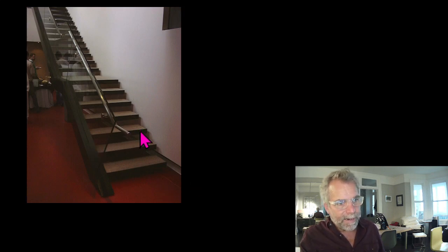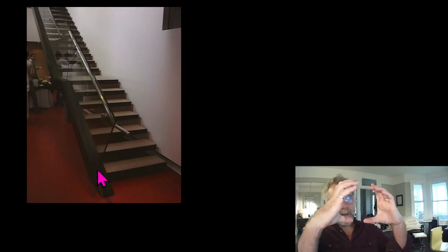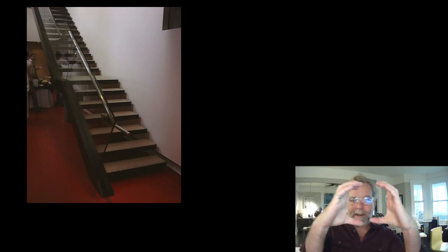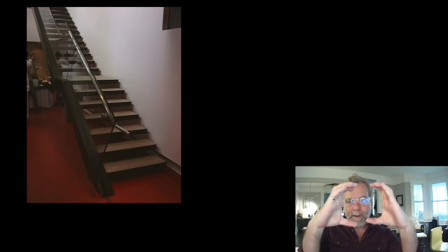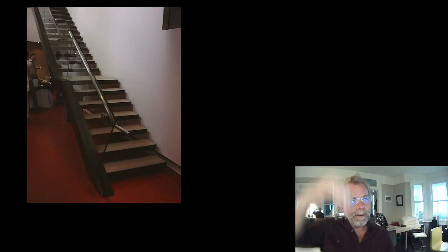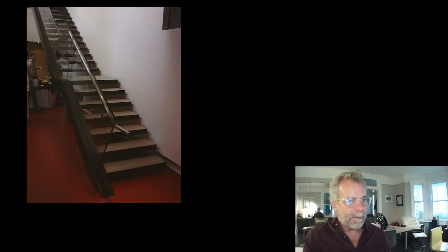The treads cantilever out of the stringer. You can see the glass guard disappearing into the stringer. The stringer was made with a pair of channels, 300 or 360 deep channels, flanges oriented towards each other, closer plate on the bottom, closer plate halfway, and the glass slipping down in between.